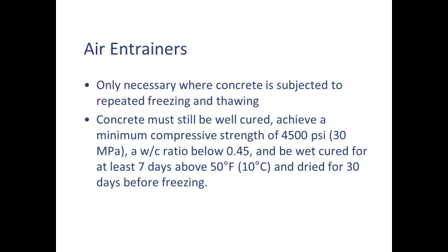Thing to keep in mind, and the reason I put this in is I just had a student of mine ask me, he's putting in a big outdoor table and it's going into 10 degree Fahrenheit weather. So that's minus something, minus cold centigrade. The concrete still needs to be strong enough. So 4,500 psi, that's 1 or 2 days with my mixes, so that's no big deal. Water cement ratio below 0.45, we got that because we never go that high.